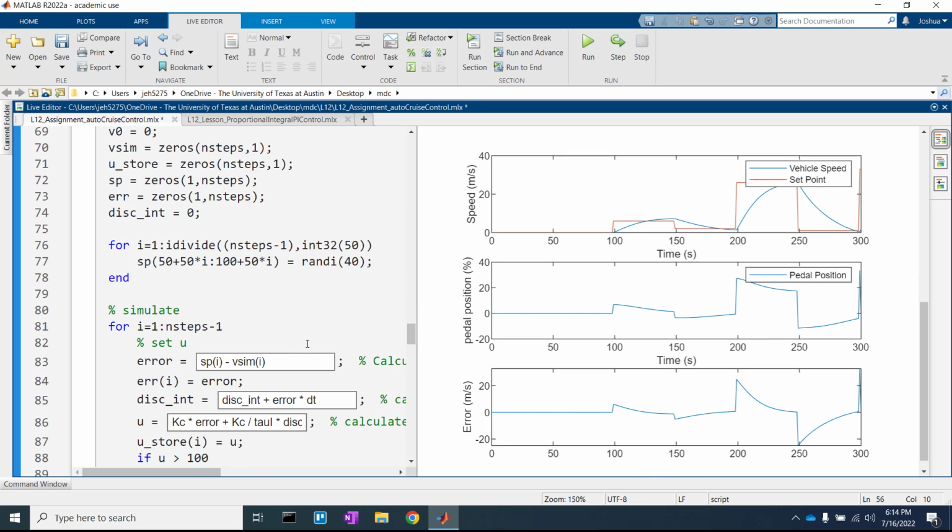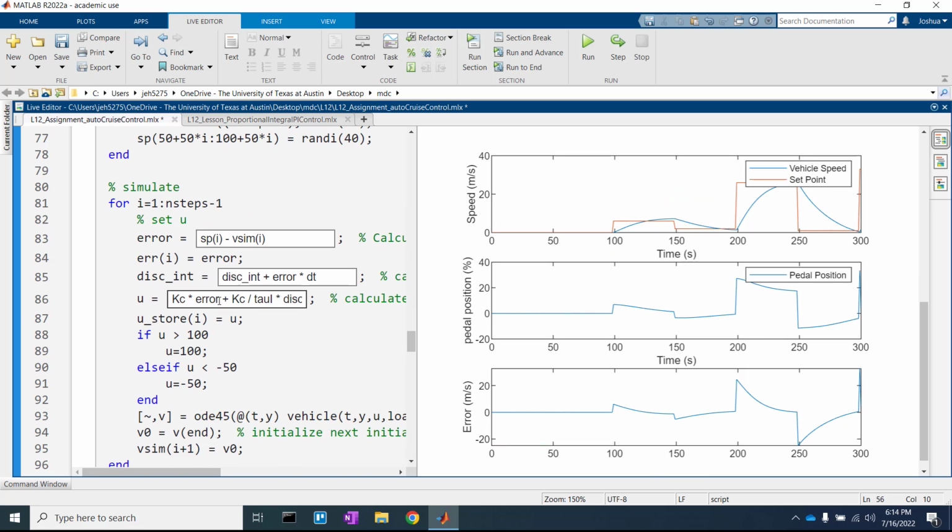Right now we want to focus on just the principles here, which are that the proportional integral controller is dependent on some proportion of error plus some proportion that depends on the integral of error. And the whole point there is that we get rid of persistent offset that occurs when we only have proportional control.